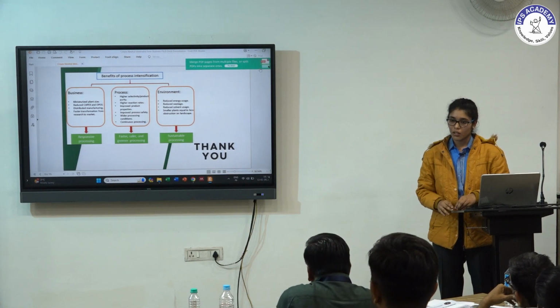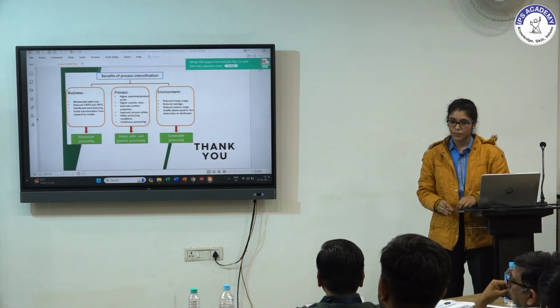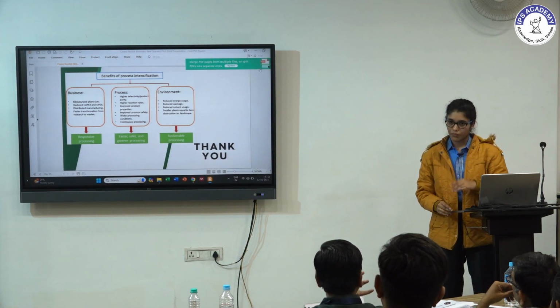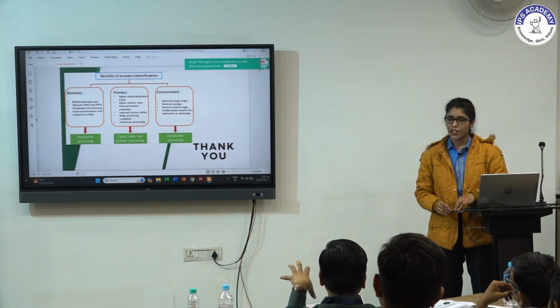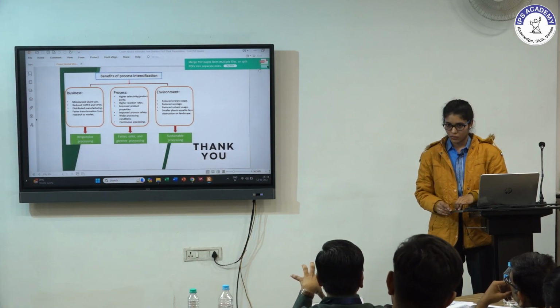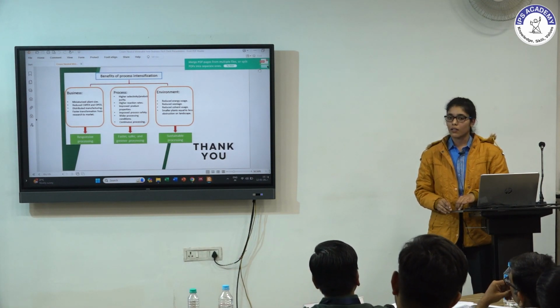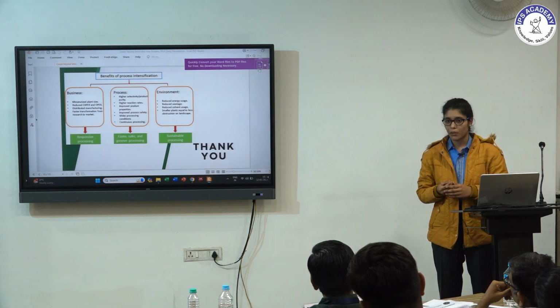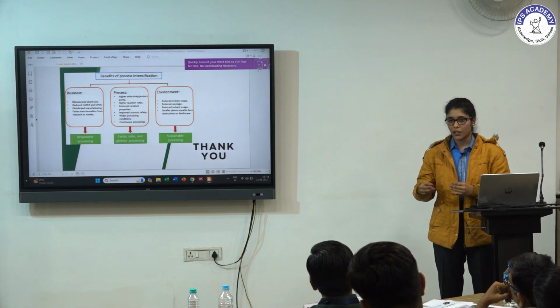You heard about it, then it's fine. Okay, and how much amount of the oil are you collecting? What is the ratio of extraction? How much amount of orange peels is required to get that much amount of the oil? So here we have taken 10 grams of dried orange peel powder along with 100 grams of petroleum ether. Then we have extracted.